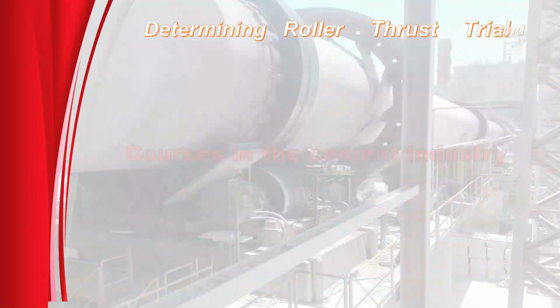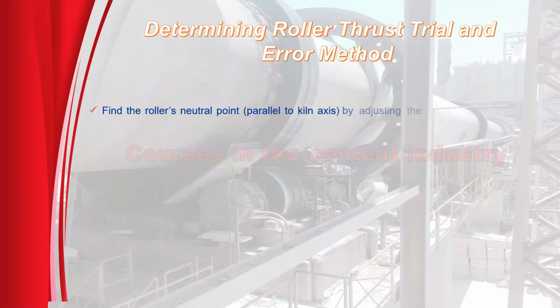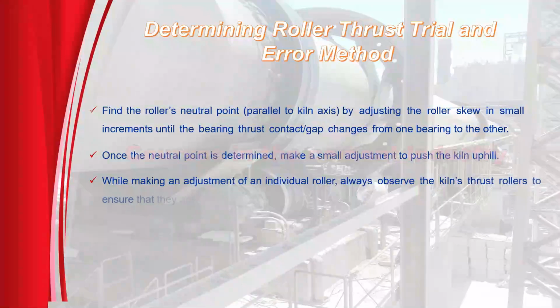Determining roller thrust: trial and error method. 1. Find the roller's neutral point, parallel to the kiln axis, by adjusting the roller skew in small increments until the bearing thrust contact or gap changes from one bearing to the other. 2. Once the neutral point is determined, make a small adjustment to push the kiln uphill. 3. While making an adjustment of an individual roller, always observe the kiln's thrust rollers to ensure that they are not being overloaded.